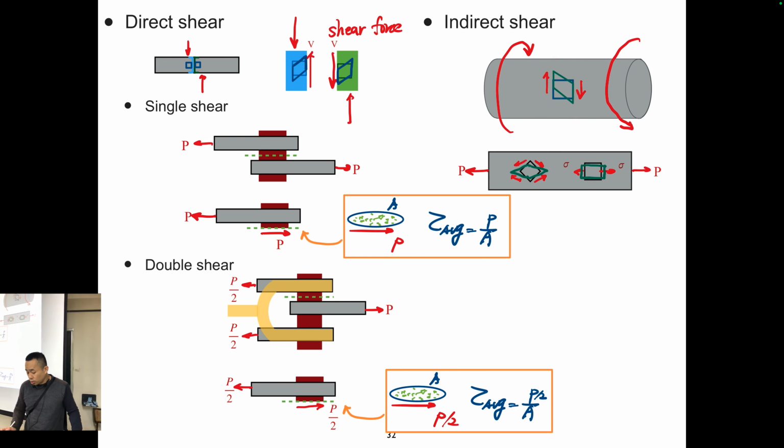Okay, so yeah, and also a very important concept is that even if you only apply normal force, you're still generating shear in the material at a certain angle. Okay, at the 90-degree angle, the XY axis angle, no, there's no shear. But if you look at another angle, the material is still suffering shear. Okay, so we will talk about this in more detail later.